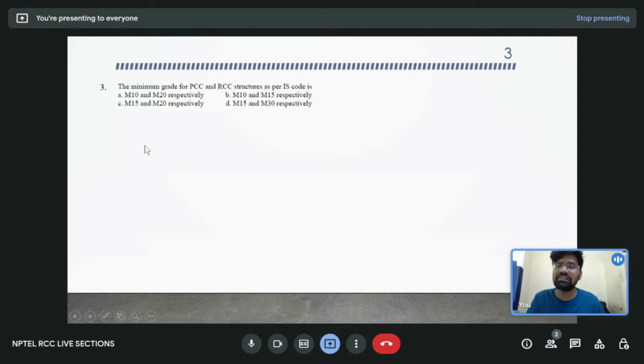The third question is, the minimum grade for PCC and RCC structures as per IS code is. You will be introduced to some IS codes during this NPTEL course of Design of Reinforced Concrete Structures. The frequently used IS code is IS 456.